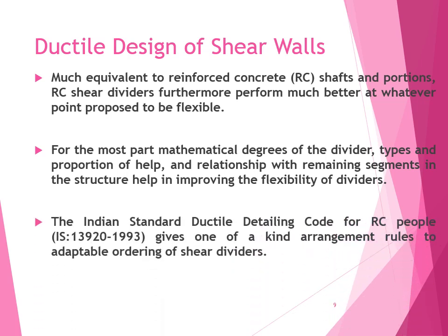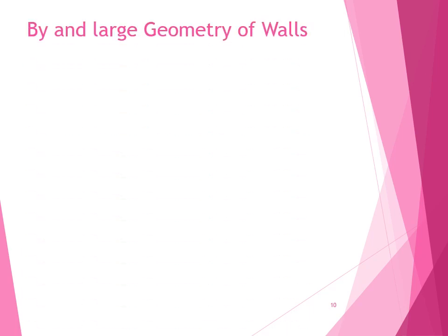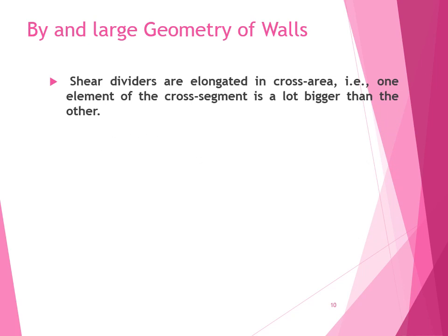The Indian Standard Ductile Code, which is IS 13920-1993, gives special design rules for ductile detailing of shear walls and the overall geometry of the walls.